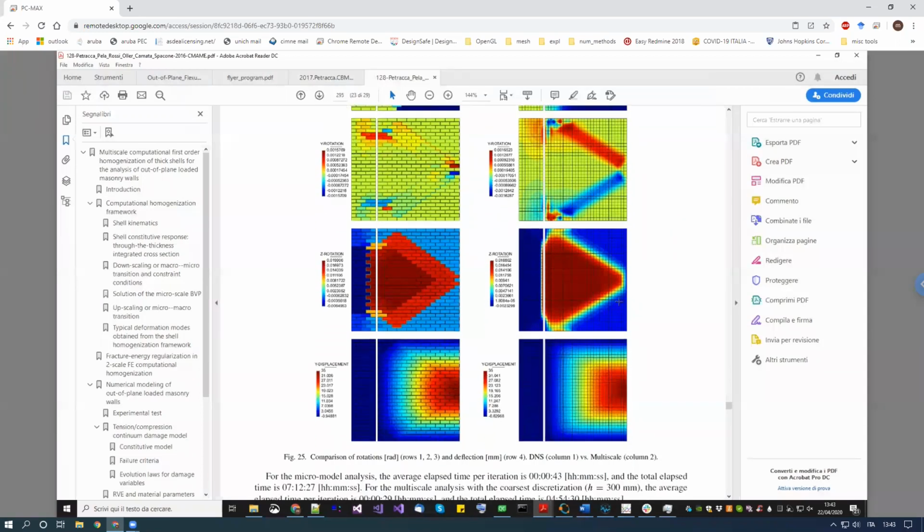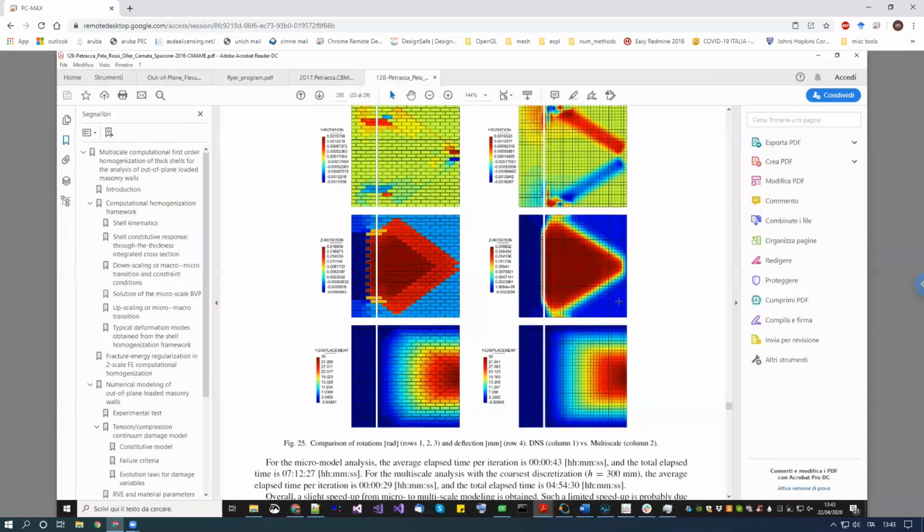Whenever you have to do with damage and strain localization, I would always use the most general purpose approach. So if for a shell you can use a thick shell, I would always use that. So the difference will be much less than what we have seen in the micro model. But since the thick shell in OpenSees is more general, and it is valid also for thin shells, I would always use that, okay? Okay, thank you so much.